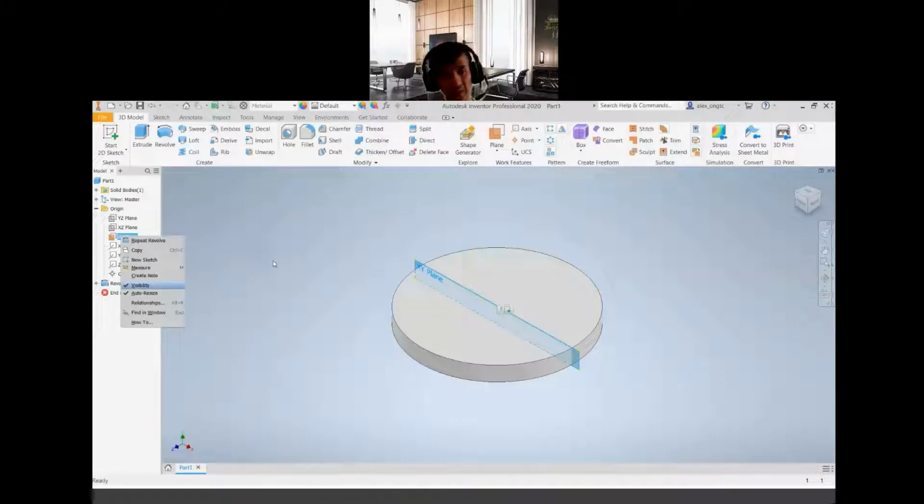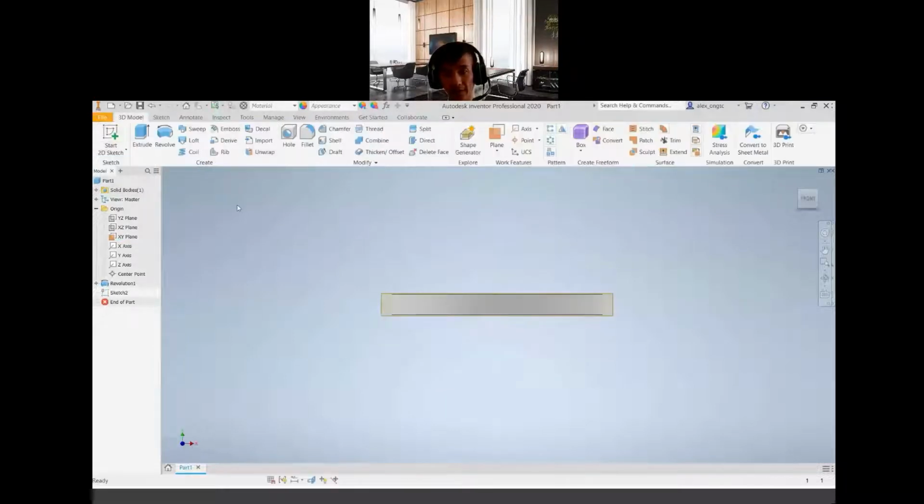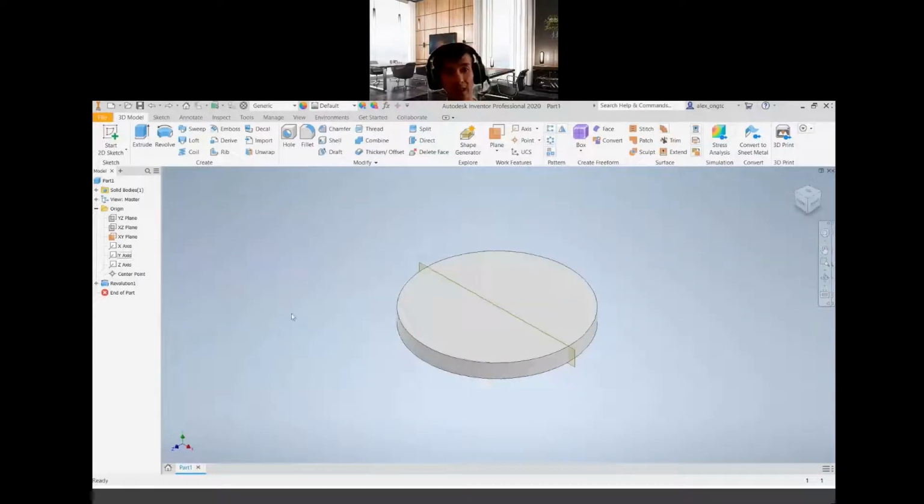So what we intend to do with this will be, I would like you to start 2D sketch. Then you can click. Okay, it straight away selects it already, sorry. I will redo this one. So start 2D sketch here, right? The intention of this work plane is, it will enable us to do a selection here. You see, we can click on this one. We want to actually create our secondary sketch on this work plane. That's why you need to turn on the visibility of it. So 2D sketch, then click.